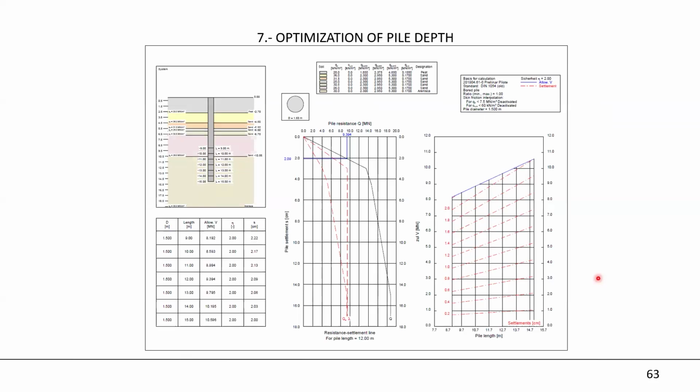Okay, we start with the structural engineer, who is in charge of the design of the overpass, and we talk about the loads there. And we divide the stratigraphy with cone penetration there. We make some estimation of the pile capacity using the German standard.